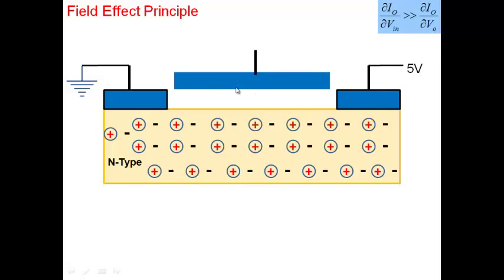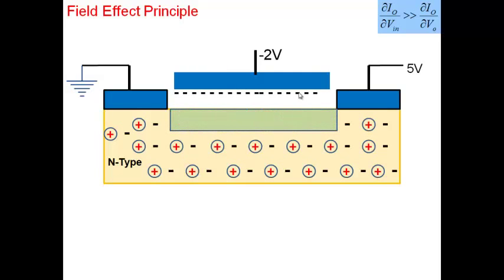Now once you have a capacitor, note that once you apply a negative voltage, you put a negative charge here. And negative charge, as you have seen, would repel away the electrons from the surface. These electrons are the ones that have traveled through the ground and are sitting on this particular plate. So thereby, you have taken a part of the surface and depleted it of electrons, right?